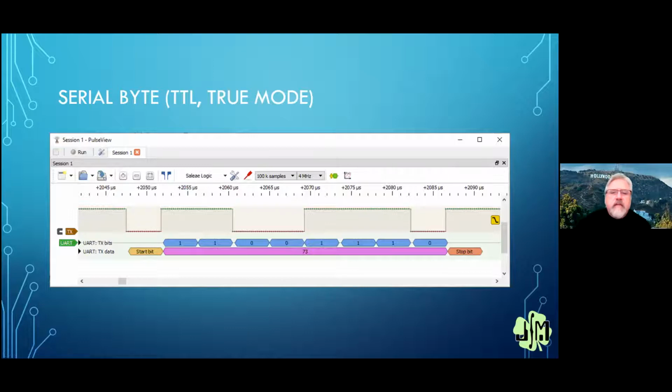Now, that ability of sampling in the middle of bits that I was talking about helped some of the folks on the stream who have probably used the SX controller back in the day, where we would do kind of interrupt driven serial generation. And what we would try to do is have our interrupt periods be a multiple of at least 5 to 7 bit periods.